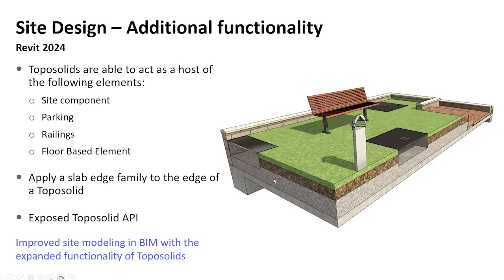So in addition to these other things, and having a layered, structured topography, we're also going to be able to use a slab edge tool to create curbs and whatnot. So I think that's a pretty interesting ability, obviously for sidewalks and for curbs and for roadways, but also for things like walls to hold back the site.